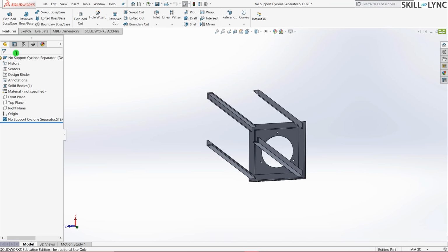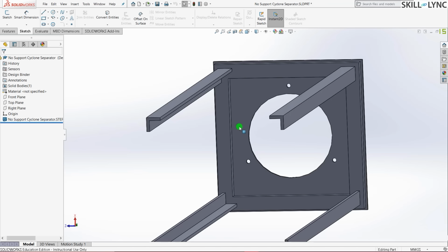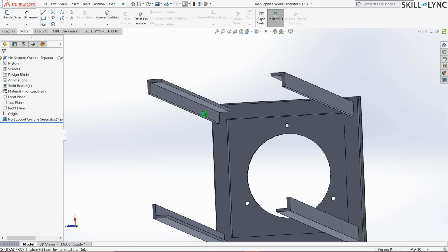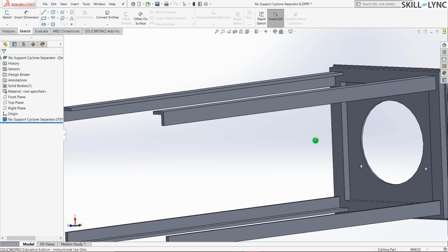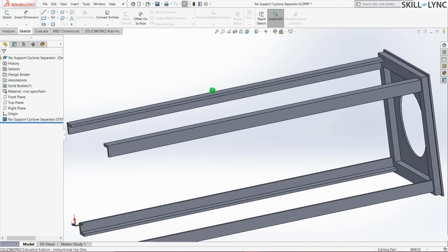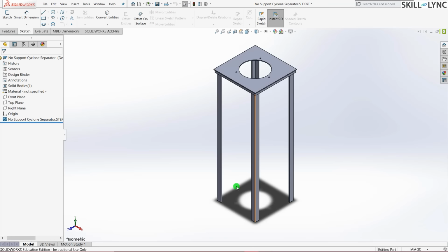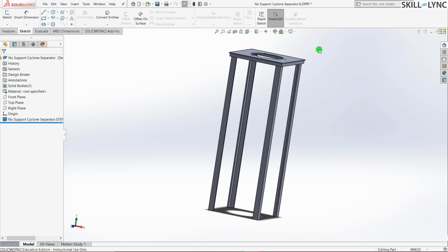So how you will be doing this is, let's just go to Sketch and select Sketch and draw the profile of the stiffener, whichever you have in your mind, in this sketch view, and then offset it and then extrude it. You will also be given the extrude thickness of your sketch. This is to ensure that no abnormally big stiffeners are made, which are just not practical.